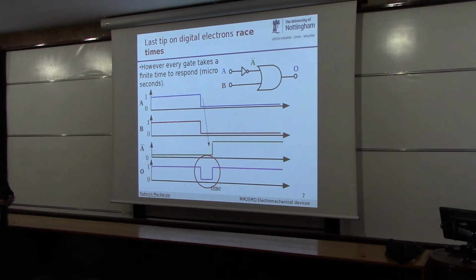So actually this circuit is giving the wrong answer for a little bit of time simply because of the delay that the NOT gate is introducing. I'm telling you about this, not in massive detail, because your digital circuits, when you design them, may not work. And this is one reason why they may not work.